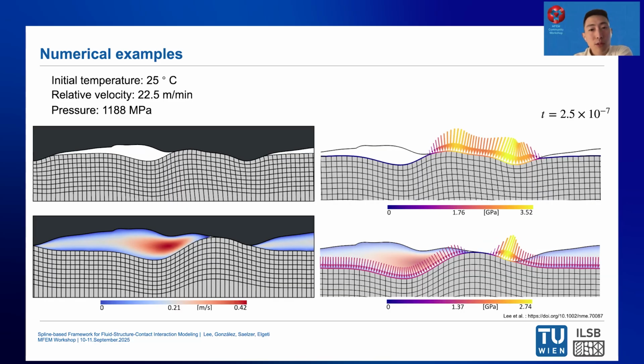Just one more. Same condition with a different initial temperature, about 650 degrees cooler. Here we see similar behavior in general, but the solids behaved a little stiffer due to the cold temperature, resulting in higher concentration in force distribution, and the force magnitude peaks at a higher value.